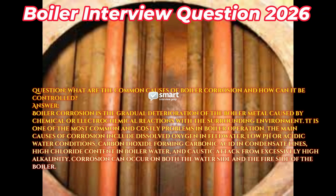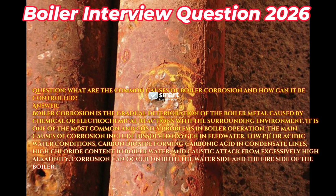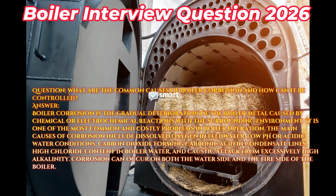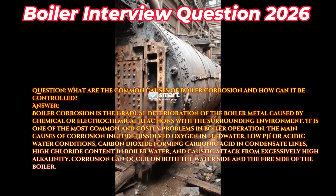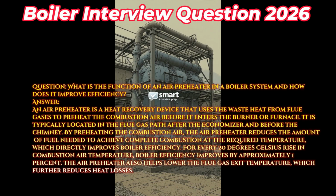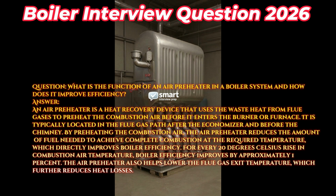The main causes of corrosion include dissolved oxygen in feed water, low pH or acidic water conditions, carbon dioxide forming carbonic acid in condensate lines, high chloride content in boiler water, and caustic attack from excessively high alkalinity. Corrosion can occur on both the water side and the fire side of the boiler. Question. What is the function of an air preheater in a boiler system and how does it improve efficiency?